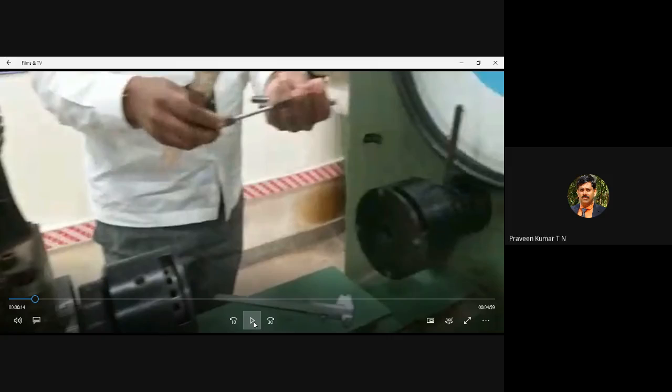The major purpose of this experiment is to get the rigidity modulus. The rigidity modulus is used throughout your engineering course, four years, or if you join the mechanical industry. Throughout your professional life, you are talking about Young's modulus and rigidity modulus. What is the material? What is the Young's modulus? What is the rigidity modulus? Or whether the rigidity modulus changes or Young's modulus changes. Most shaft materials should have higher rigidity modulus because shafts are subject to torsion loading, like your fan rod. A fan rod is also subject to tensile loading as well as torsion loading.